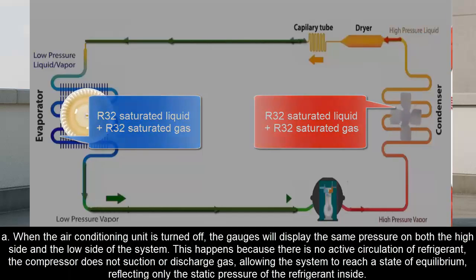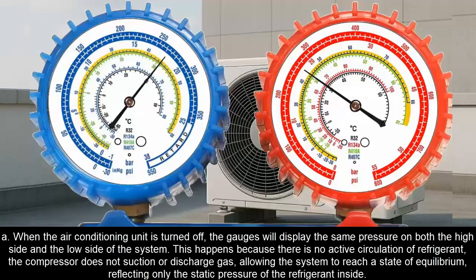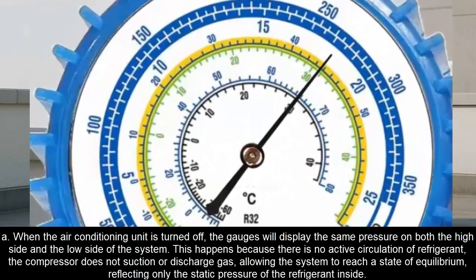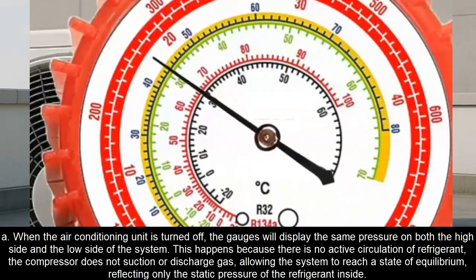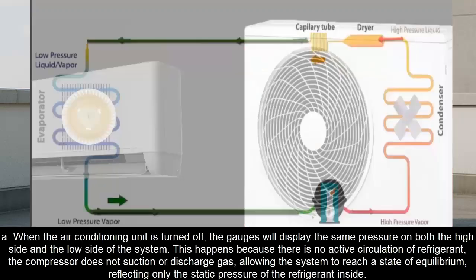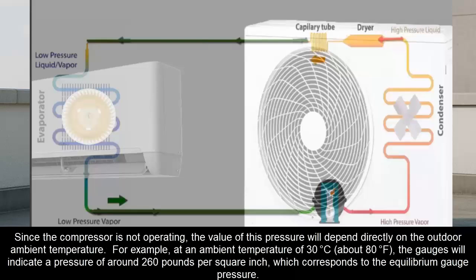A. When the air conditioning unit is turned off, the gauges will display the same pressure on both the high side and the low side of the system. This happens because there is no active circulation of refrigerant. The compressor does not suction or discharge gas, allowing the system to reach a state of equilibrium, reflecting only the static pressure of the refrigerant inside. Since the compressor is not operating, the value of this pressure will depend directly on the outdoor ambient temperature.